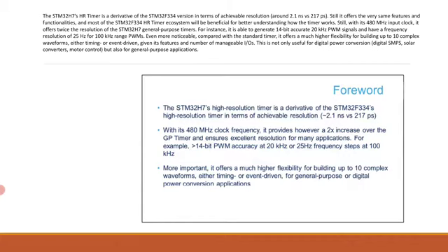So although we talk about a single HR timer, it is actually made up of 16-bit counters that can either be independently or synchronized, each of them having an independent clock prescaler. It is equipped with a total of 24 compare and 10 capture units and can control up to 10 outputs. Have a look at this.